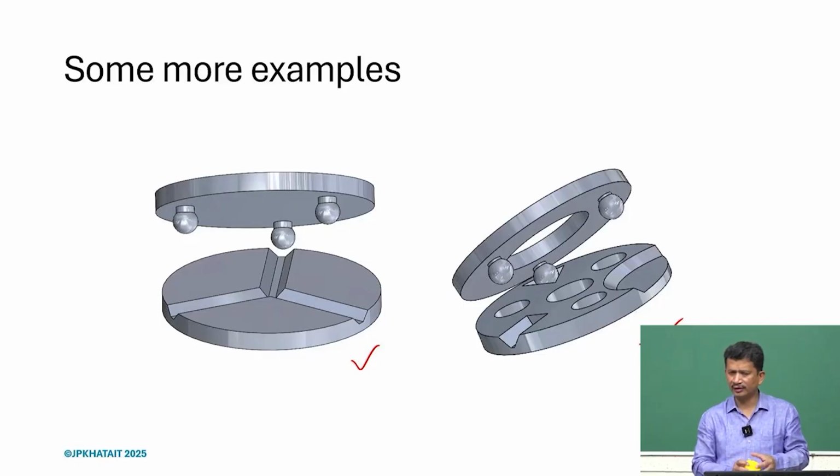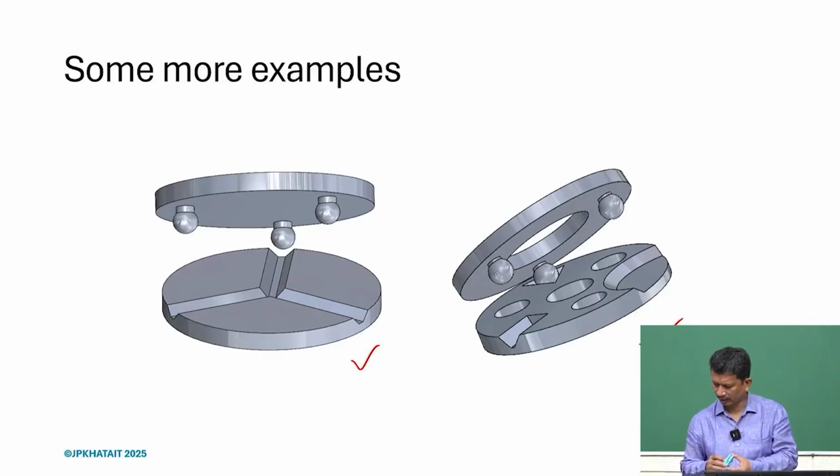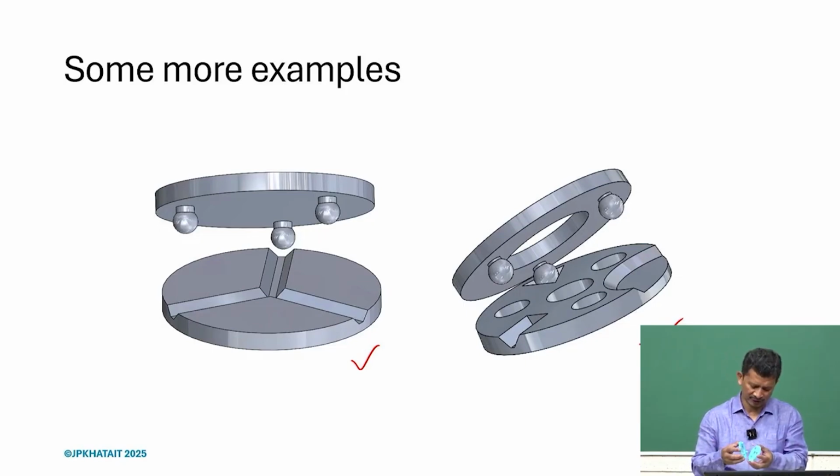These are very old designs, mainly used in optics. It's called a kinematic clamp, or even a Kelvin clamp. Here you see 3 times 2, so a total of 6 contacts. There is another example: a tetrahedron hole, a spherical and V, and a ball and flat end. So, 3-2-1 configuration again, and this also gives me the same kind of repeatability.